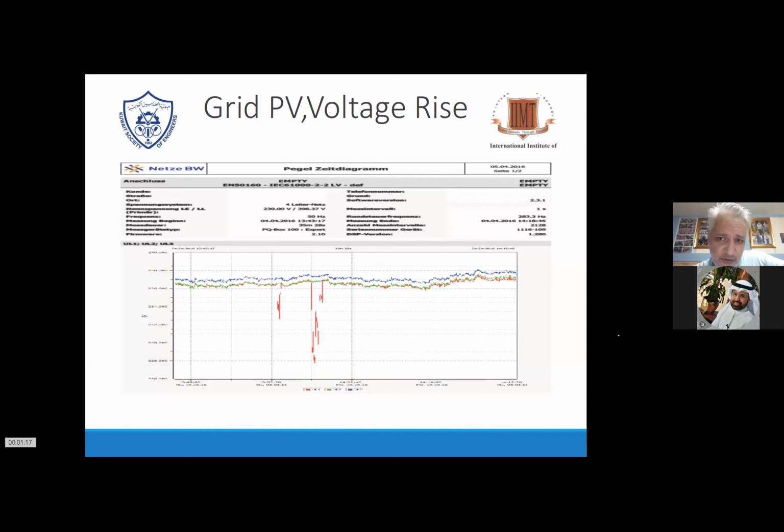But when they put it to the 1 second interval, you can see the red dots. One of these inverters created a problem in phase 1, 2, or 3, and when that happened you had spikes going down. That was enough that one of the other inverters picked up the noise in the AC grid and switched off. By doing so, all the other inverters triggered the same problem, and then 3-4 times a day, the whole system shut down, or partially.